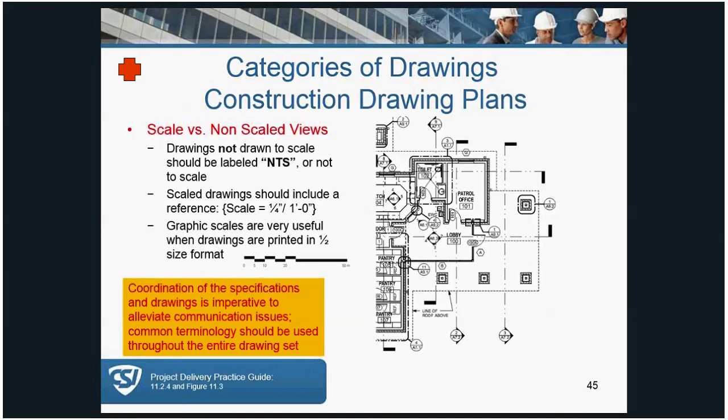There are scaled and non-scaled drawings used in the development of construction documents. Scale drawings will include a numerical scale, for example, 1/4 inch to a foot, or a graphic scale, which is commonly used since drawings might be printed half-size or issued as PDF.